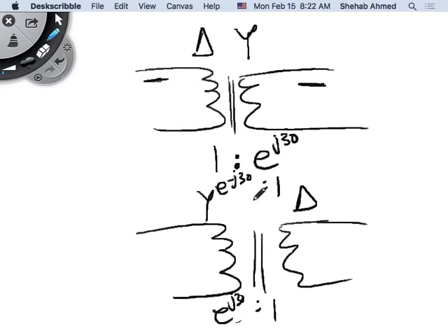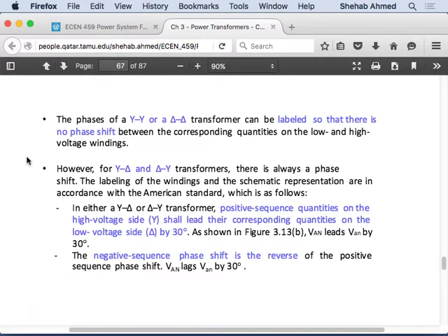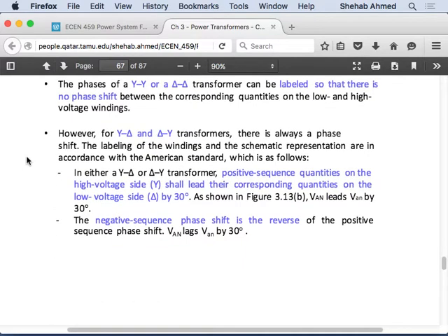You can move things, collect the impedances, move the impedance from the primary to secondary, secondary to primary, and then you still have to make sure that you deal with the voltages and currents. But the impedances, when you transfer them, are based on magnitude only. You will not change the angle of the impedance, right? So the transfer from primary to secondary will still be based on the turns ratio squared, right? We will see. I think when you solve the examples, it will be clear. Okay, so that's what we're trying to reach. And then we will just give you the proof and solve some examples today. That's the objective of today's class.